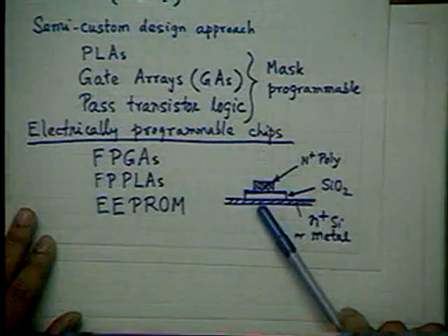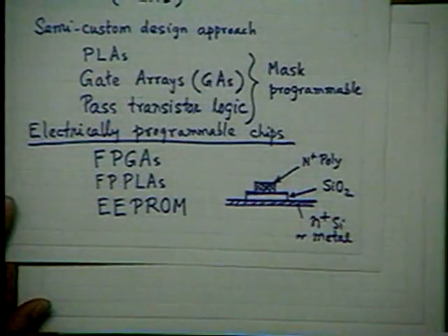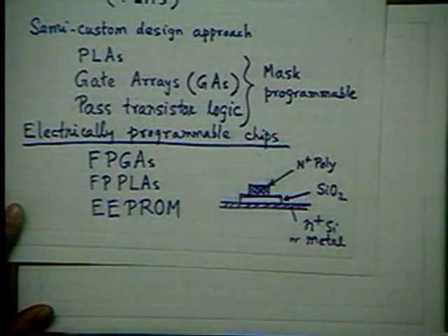What I do is apply an instantaneous large voltage at these so-called antifuses, and automatically it becomes practically a short, 200 ohms, 300 ohms, which is practically a short circuit to a MOSFET. MOSFETs are normally very high resistance devices. So 200, 300 ohms is practically a short circuit. So you can create the nodes in your lab. I want to create a node, a connection, and that I can do in the lab.